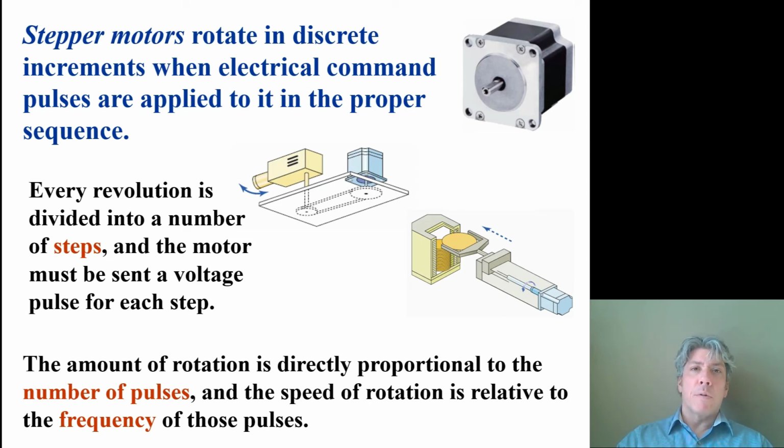Sometimes stepper motors are used with position feedback to make sure they've reached the intended position, but often they're used without. Now, a disadvantage of this motor: it's basically like a solenoid in that to hold a position, you keep applying current to the particular coil that the motor is supposed to hold position at. The problem with that is all that electricity and power goes into heat. Energy is conserved, so if electricity and power go into the motor, it must change into some other form, and it changes into thermal energy, or what you probably call heat.